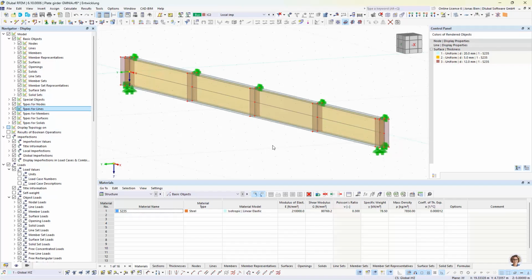Okay, so now last question is, how do we combine all these imperfections together? In Eurocode 3 part 1.5, we have a combination rule for equivalent geometric imperfections. We have one primary imperfection that we assign with 100%, and the other ones we take 80%. But just to make things a bit simpler here, I would just take them all with 100% amplitude, because in most of the cases, there's always 1 or 2 imperfections that are not really relevant or critical for the end result.